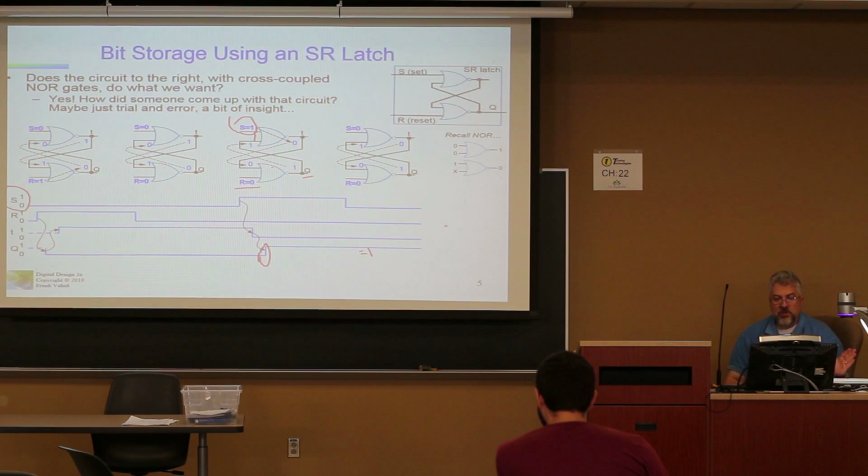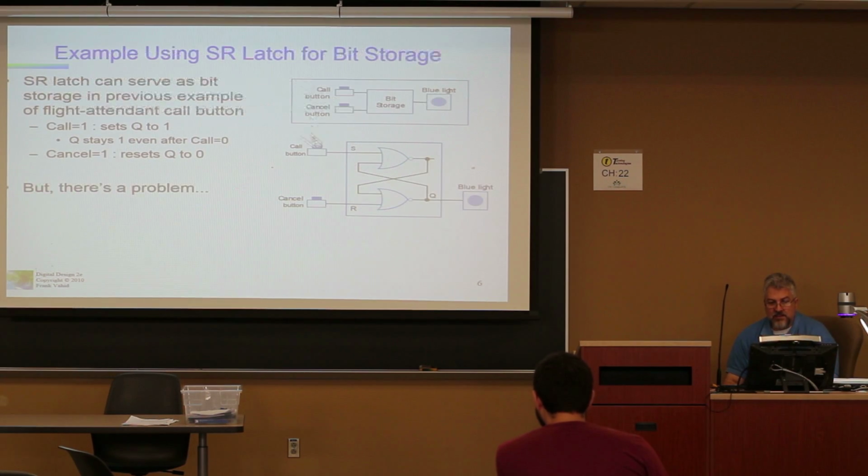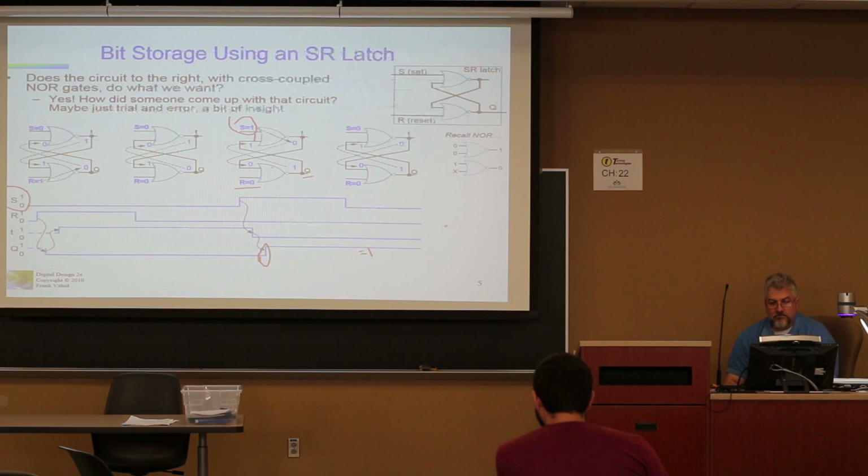So what's the important thing to note here? The important thing to note is that we use this reset line to bring this to a known state. And here's the known state. All right? We hit the reset line here. The known state, here's our S is equal to 0. At this point, our value right now is 0.